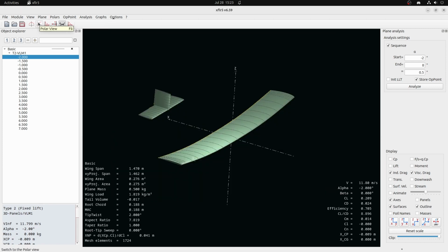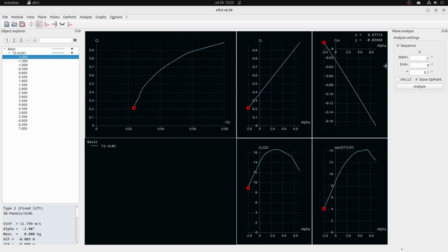And generally, what I would do is look at the polars, and if we get the type of information that you expect to see, then probably the errors aren't particularly significant. But before we finalise the design, we should go back and just try to check that we're not missing something important. There are various polar graphs available. For example, we have lift versus drag, and the lift-drag ratio versus the angle of attack, and other information like the pitching moment versus either alpha or speed.